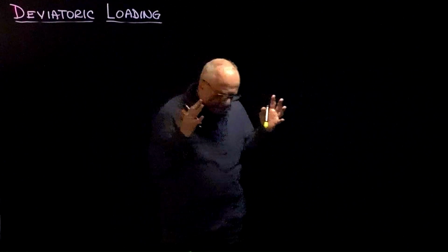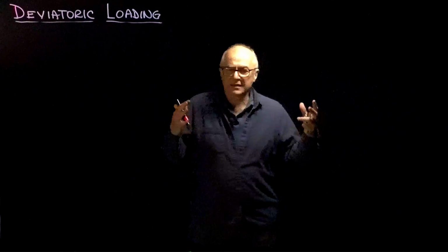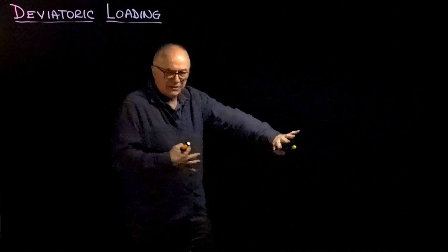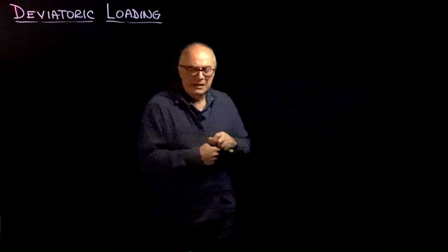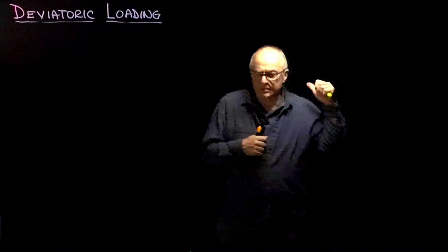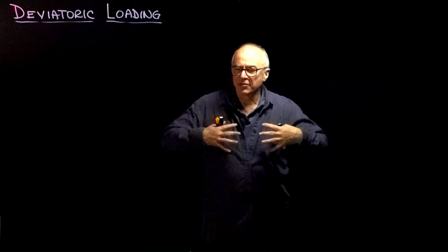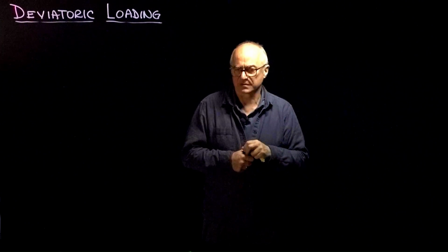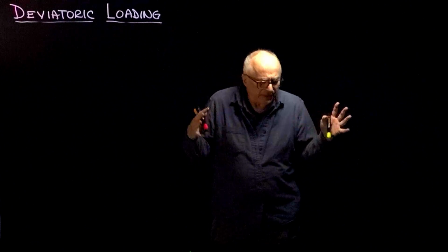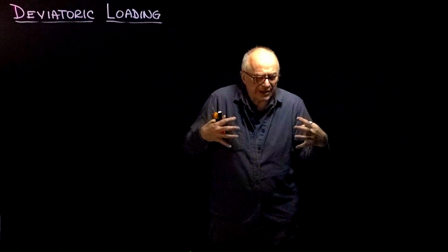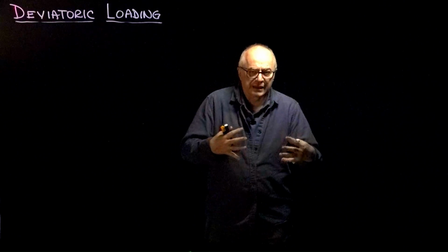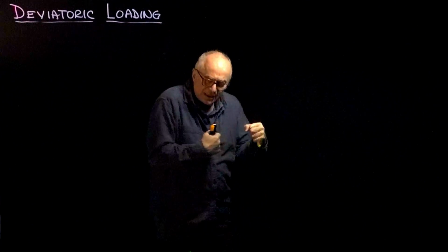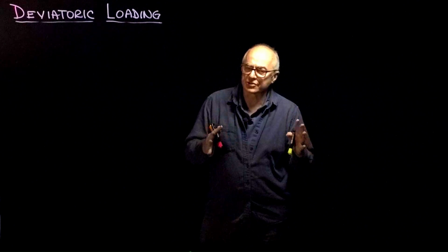But imagine yourselves being in an elevator and somebody behind you is trying to come out. If there are only 2 or 3 people, you move to the side and the person can come out. However, if a person wants to come out and is all the way in the back in a packed elevator, few people will have to exit for the individual to come out. That is dilation. However, if for whatever reason there is very high pressure and you cannot expand, and that person still has to come out, well, you're going to squeeze yourselves for that person to exit. So under high pressure, there will be no dilation.